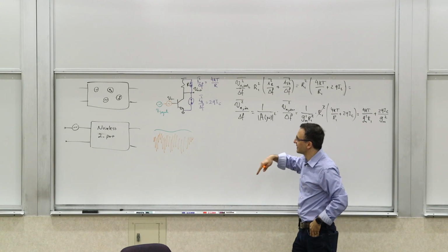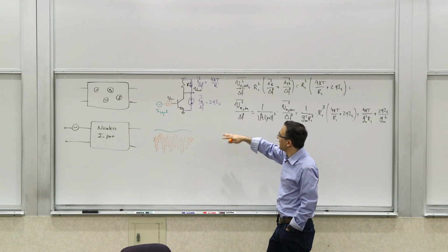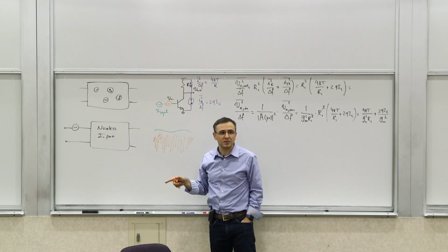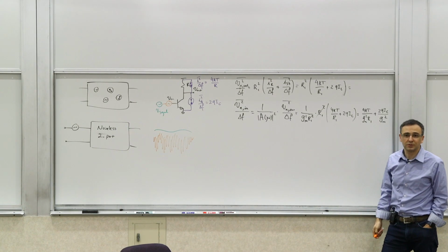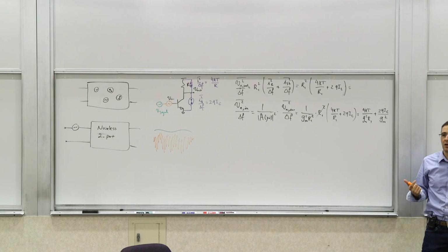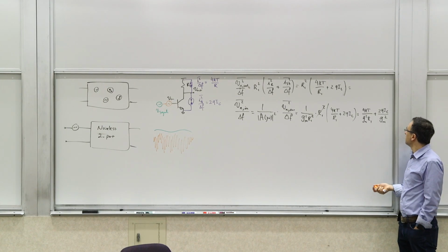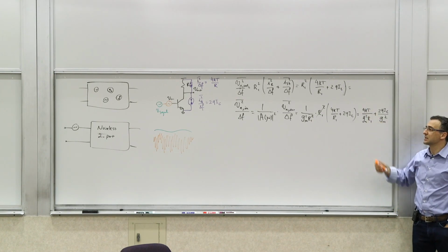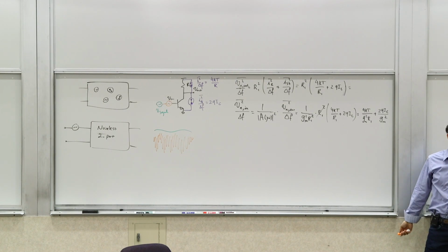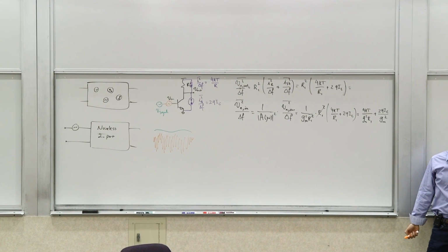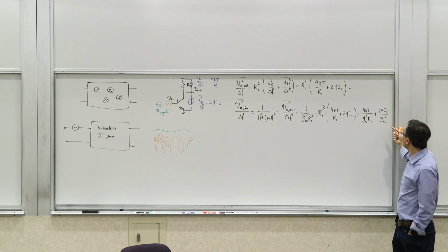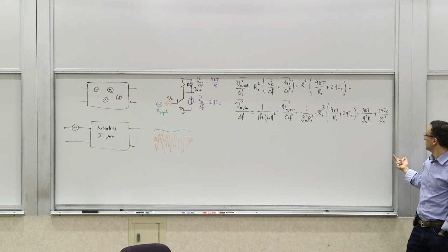Again, we're not getting into that depth. But anyway, going back to this conversation, you see that this is useful because it allows you to compare it with a signal. So let's see. If I wanted to minimize my input referred noise, what do we need to do? Look at the parameters, right? K we cannot change, that's the Boltzmann factor. Temperature is whatever it is. Of course, I can go to lower temperature. Yes, it helps you. And if you want to get really low noise stuff, those are really operating at really low temperatures. Cryogenics, right?